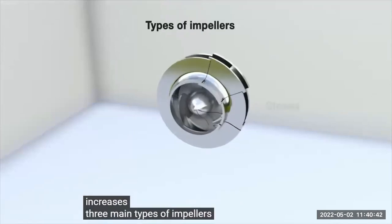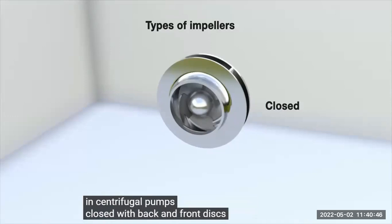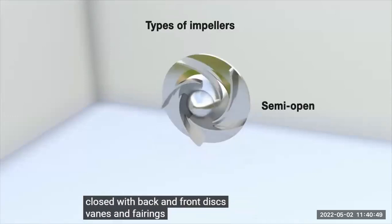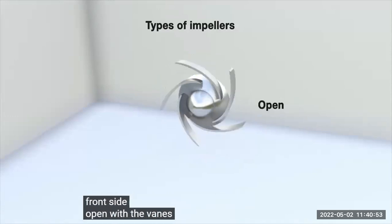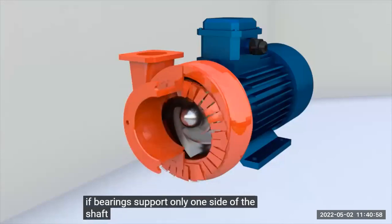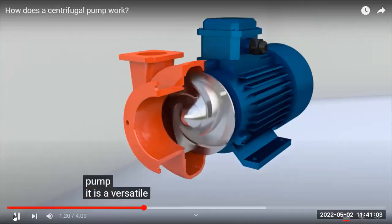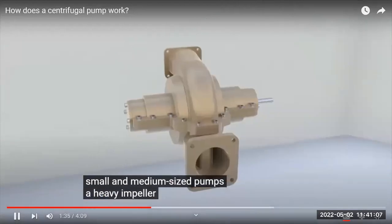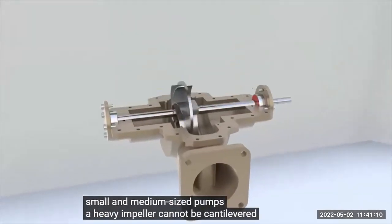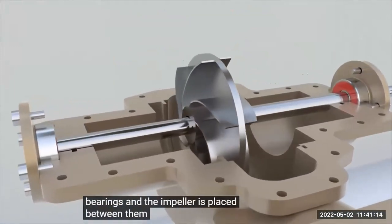Three main types of impellers are used in centrifugal pumps: closed, with back and front discs, vanes and fairings; semi-open, with the vanes free on the front side; open, with the vanes free on both sides. If bearings support only one side of the shaft, the pump is called a cantilever pump. It is a versatile design that is used in small and medium-sized pumps. A heavy impeller cannot be cantilevered. In this case, the shaft is mounted on bearings and the impeller is placed between them.